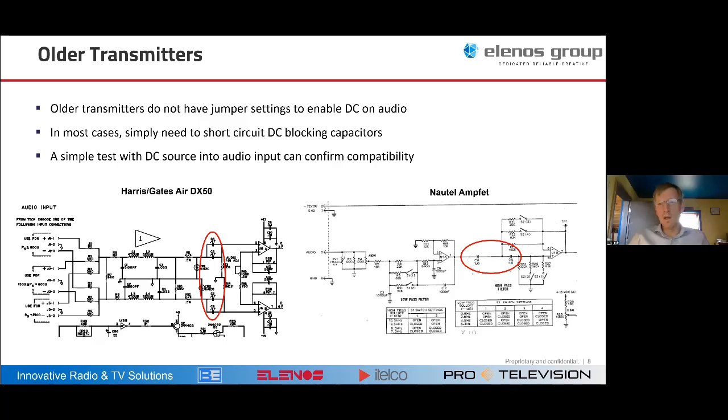Yeah, I'd like to comment, if I can, that with KBLA in Los Angeles on 1540, we put in a Harris 3DX50 that had the MDCL built into it, and we turned that on. It seemed to be working great. Power savings were looking pretty good, but we found in the morning we had complaints from listeners that the station was being interfered with by a co-channel over in Arizona.